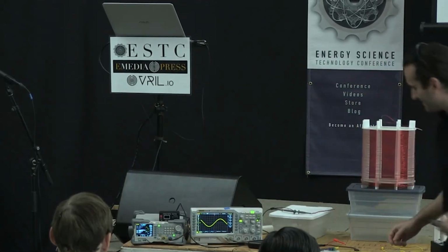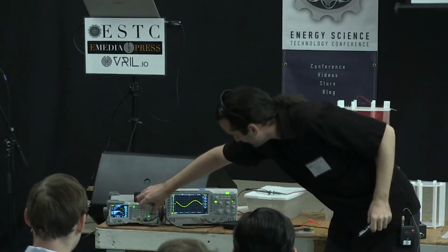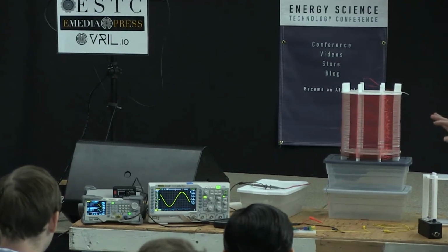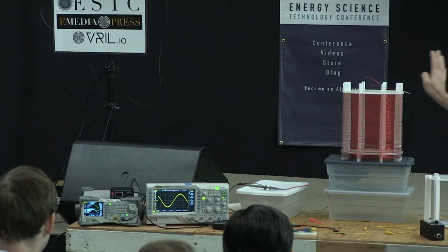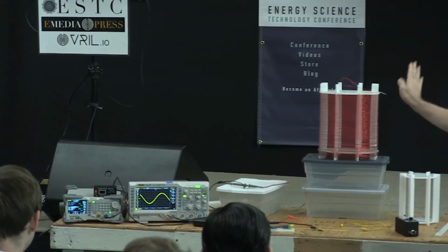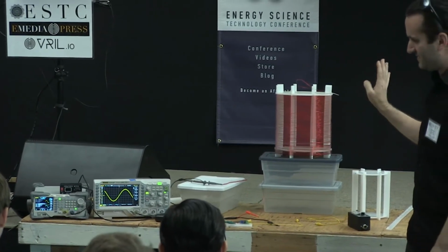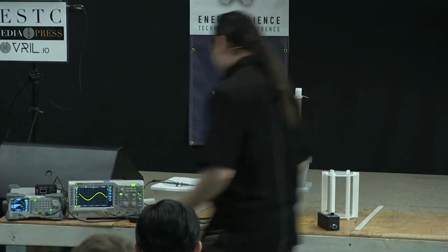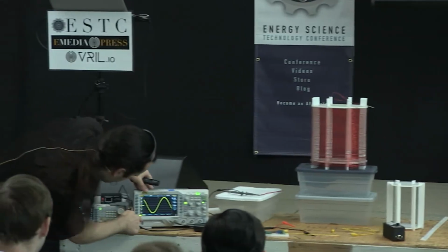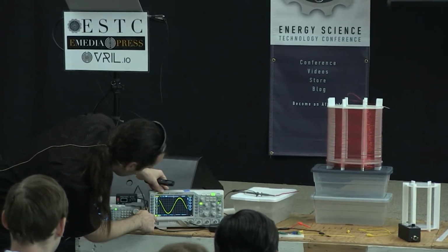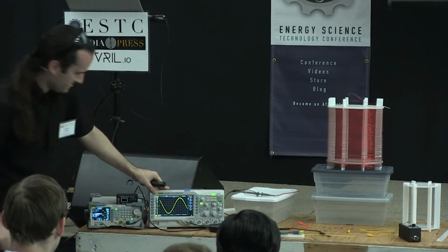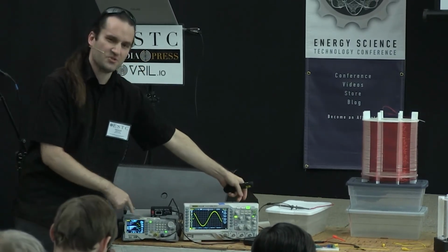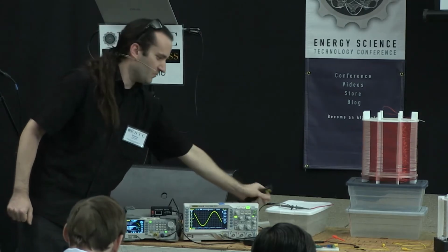So if you'll notice, I can tune this up to a high amplitude, and then just moving your hand even a pretty good distance away, you'll see how far I'm detuning the coil. That's changing the frequency by tens of kilocycles. And what else can we do with that? If we look at the power on here, the scope is set to 5 volts per division, so we're probably about 50 volts right here. The function generator is putting out 20 volts, less than 1 watt.